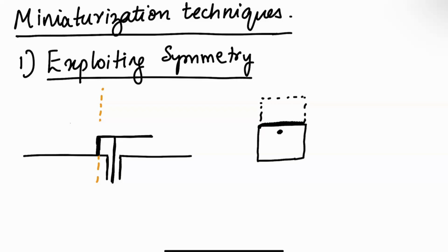Now in reality, of course, the shorting pin will add some inductance, so you still have to tune the structure. You can't just put a pin or a short circuit there and assume it all works well. And there are different ways to put a shorting pin. You can put multiple vias, or you can even put just a single via out here, and that's decent enough. That will still make it resonate as long as you tune this well.